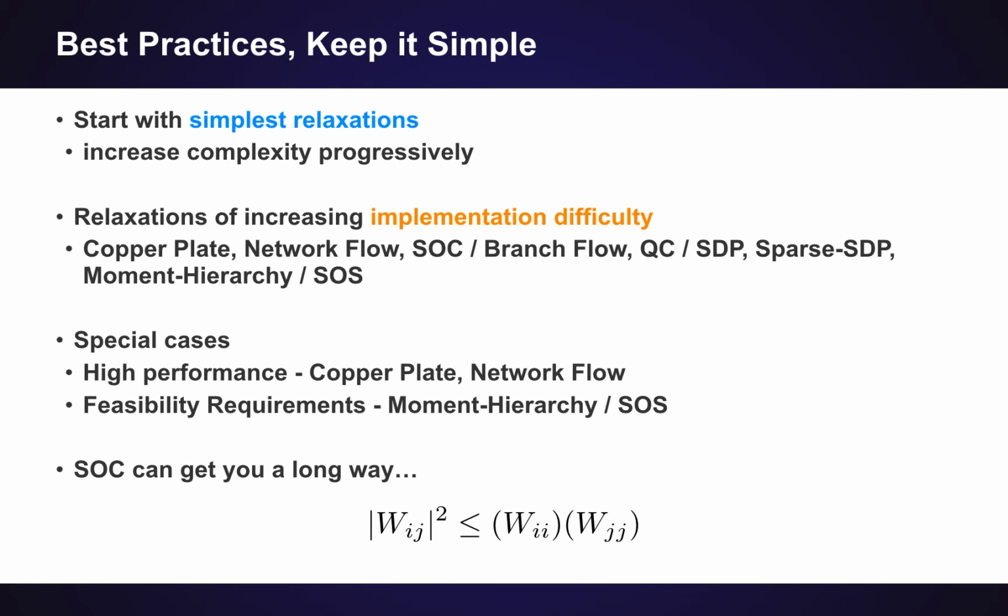So I'll note that semi-definite programming, which is a very popular method in power systems these days, is still very much an active area of research in algorithms. And so with those methods, sometimes you run into difficulties with numeric stability because you're using academic codes. They're improving all the time, but that's a very big reality of trying to solve these, whereas with the simpler methods, like second order cone, the solvers are readily available, they have a lot of industrial backing behind them, and they're used in real world scenarios a lot, so they're more robust in the engineering sense of robustness.